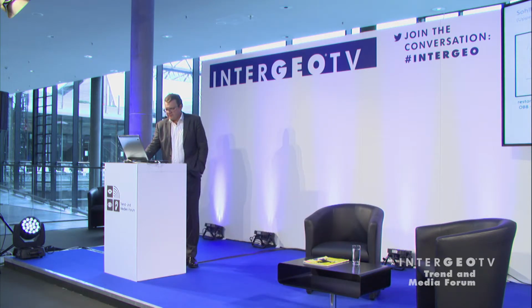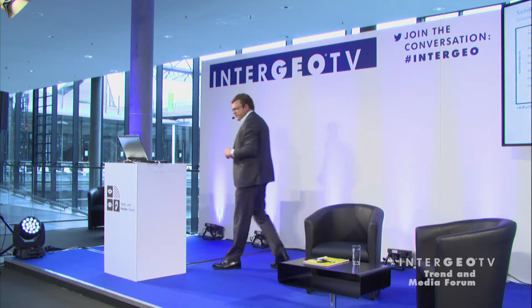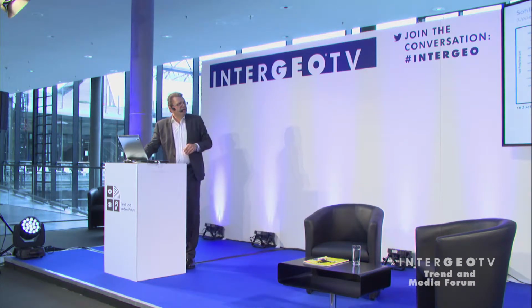It has been installed since November 2013 and gives us at some spots an idea of the movement. In the first 6 weeks we had a movement of about 1.2 millimeters, and the tunnel is now stable on these spots, so we can prove that there is no abnormal situation and no abnormal movement.